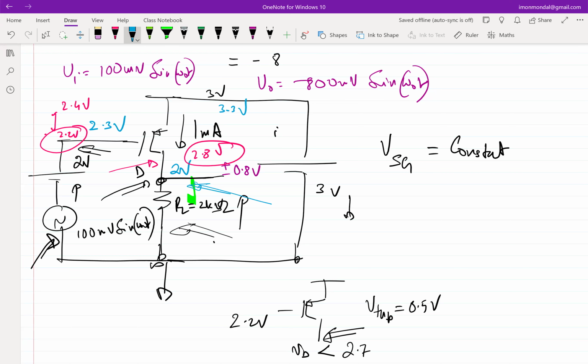Right? So if that spec changes, what is it that will go and change? Let's say both the source and the gate voltage I will increase by appropriate amount. Whatever is the appropriate, you calculate and figure out. You analyze and figure out whatever is required to keep the transistor in saturation. But you see that, if I flip the argument round, I can say that for a given battery voltage, there is probably a maximum amount of gain that you can get. Because if you want to get higher gain, you have to increase the battery voltage.